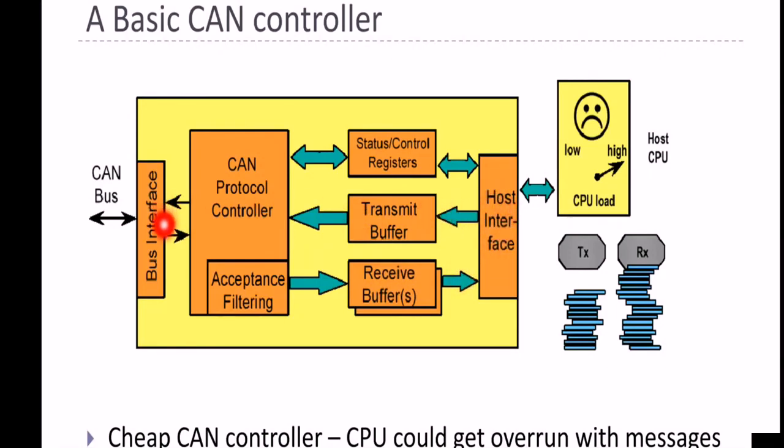Say for example, on the CAN bus we have one node, say a braking node, and this braking node transmits the data to the engine node. Here the engine node will be the host interface. So it goes to the processed data like this, and it will keep counting the TX and RX for error confinement, to check for error fault confinement. It will also see the CAN CPU load as low or high, so it will keep monitoring the CAN bus load.